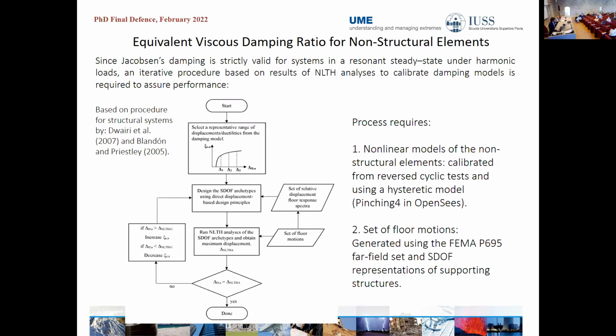So this process requires nonlinear models of non-structural elements, which were calibrated from reverse cyclic tests. In our case, we use the Pinching4 material model in OpenSees, and a set of floor motions, which we generated using the FEMA P695 far-field set and single degree of freedom representations of supporting structures.